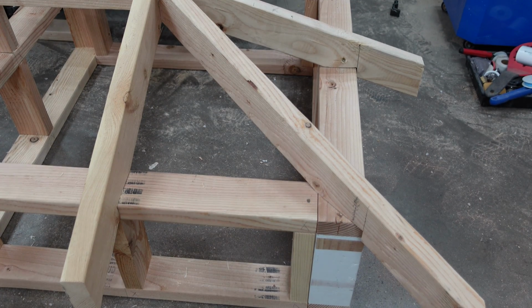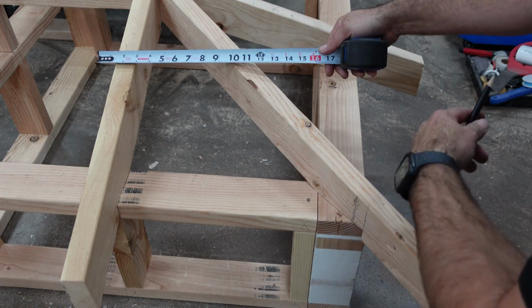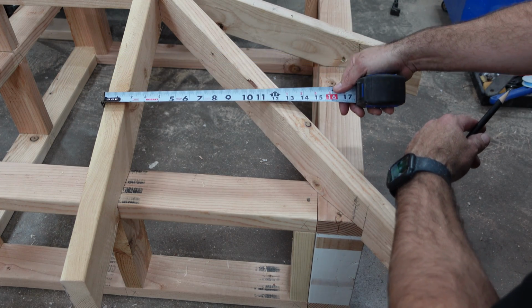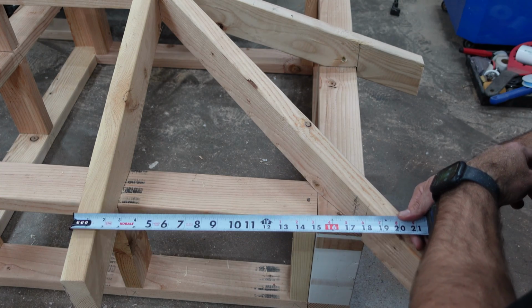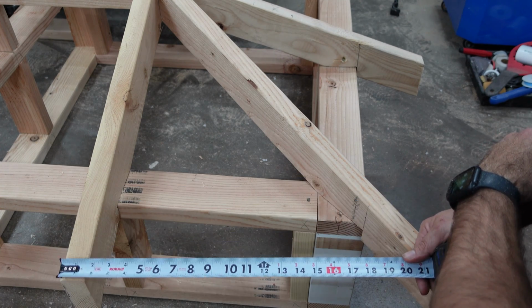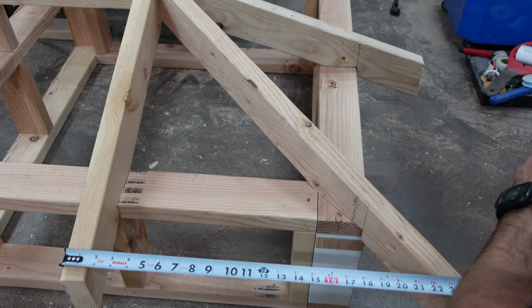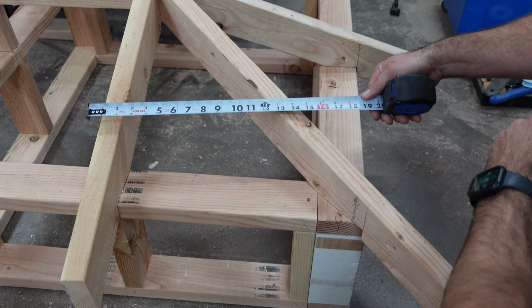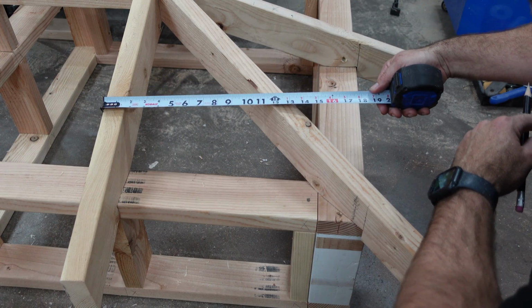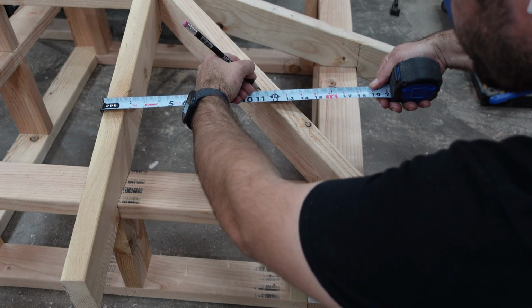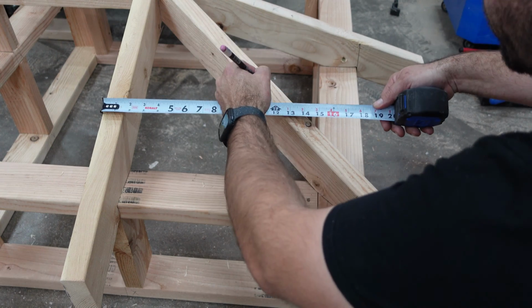For the hip jack rafter, I would pull layout from one truss on layout and mark it on the hip. But I don't have any more trusses than this one on the end and the one touching the hip, which isn't typically on layout. So I pull a dimension off the rafter that is touching the hip rafter, and even though I would normally have a 16-inch on center layout for rafters, my model is kind of small, so I will just arbitrarily make a mark at 11 inches.